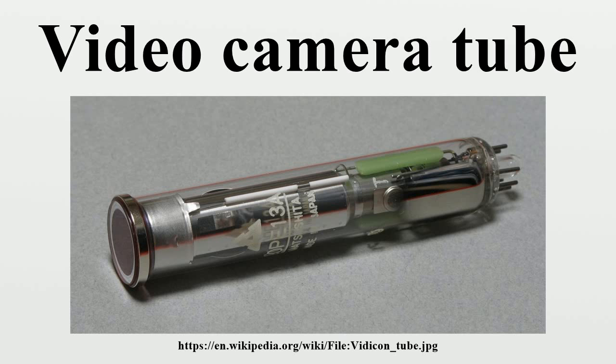The output from the detector is an electric current whose magnitude is a measure of the brightness of the corresponding area of the image. The electron image is periodically deflected horizontally and vertically such that the entire image is read by the detector many times per second, producing an electrical signal that can be conveyed to a display device, such as a monitor, to reproduce the image.